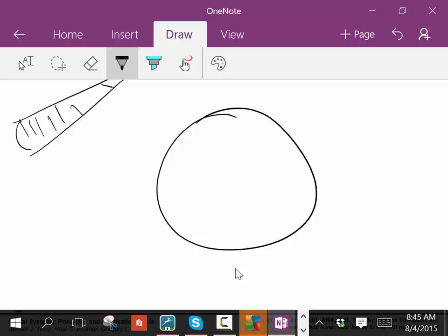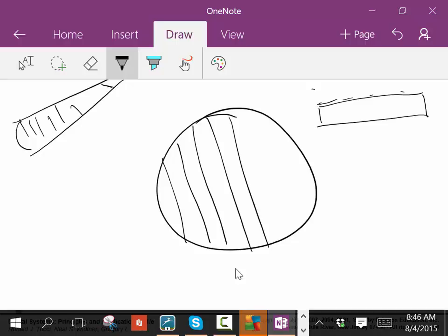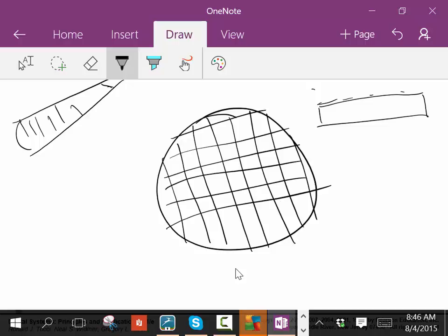And each wafer, if you look at it from the side, we place a mask over it, and we expose it with a gas. This gas sets up pockets of what they call positively charged material or negatively charged material. Then we place another mask on it, and we repeat the process. We keep doing that until the circuit is on the chip. Now, this piece of silicon is going to be cut into small little chips. The pieces that are not complete, of course, are thrown away. And each one of these is a particular circuit.